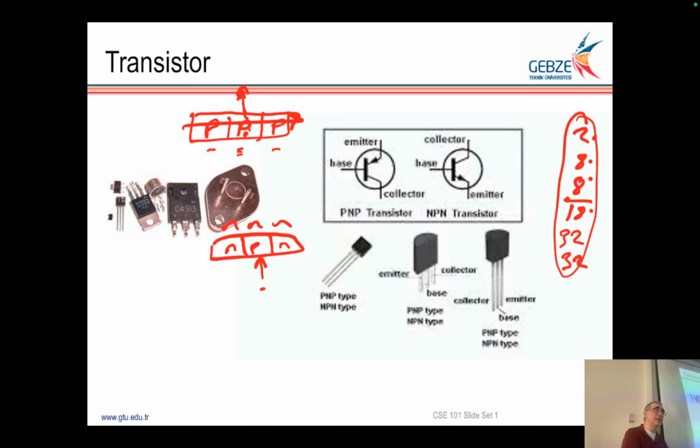They put a mask, the metal vapor is put in the oven. I am simplifying it. It's not that simple, of course. Those atoms are deposited onto silicon. They change the mask, do it again, second run, third run, so they can manipulate the silicon by creating lines, rods, and conductors, etc. It becomes an integrated circuit or transistor.